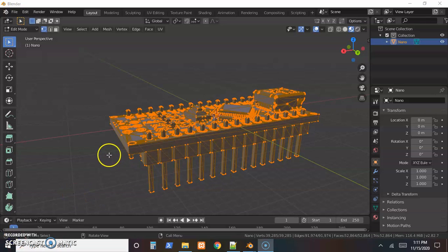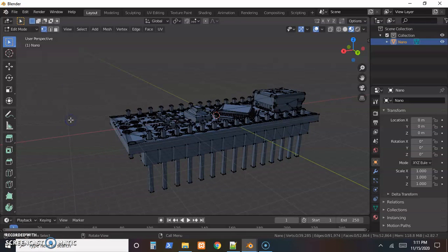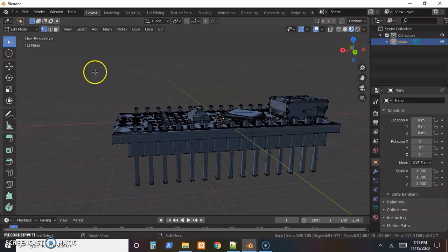And I'll just get started here. This is one place that I really like the freeform selection. If we leave the cursor somewhere in the viewport and push W, it'll switch between box, circle, or freeform selection. Then we can just drag and define the size we need, and all the freeform selection has to do is touch the thing.